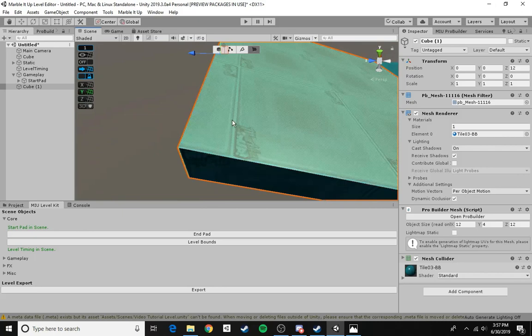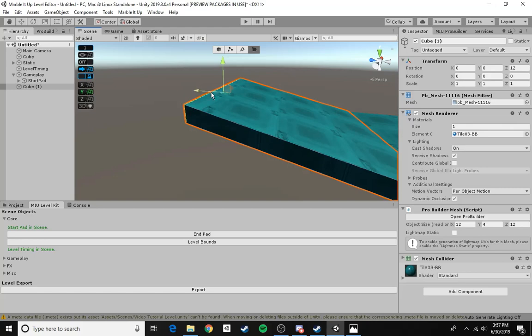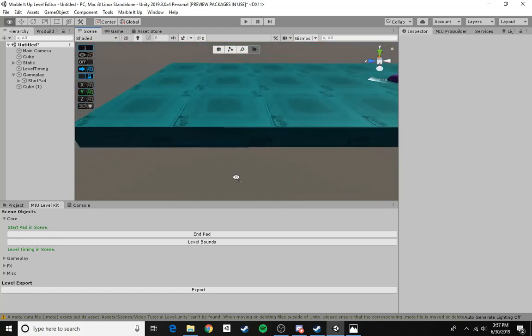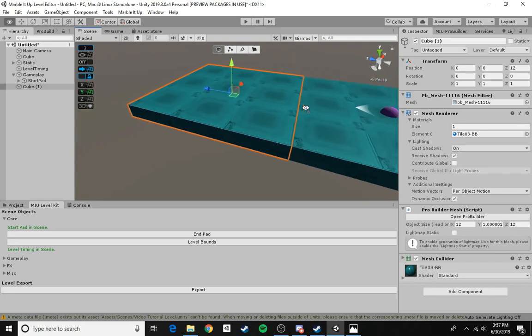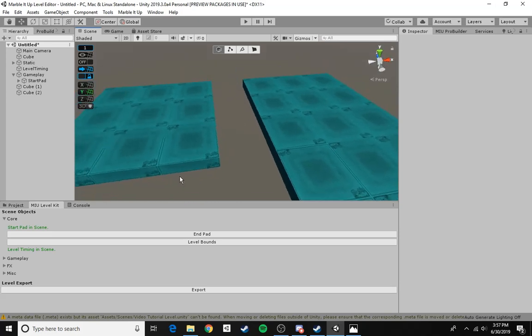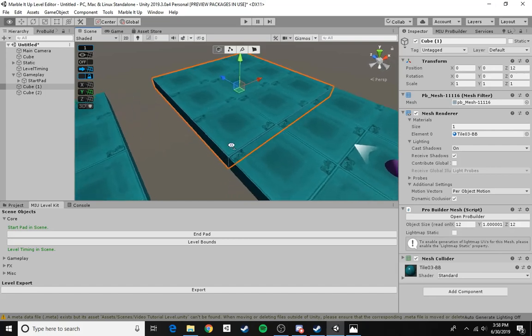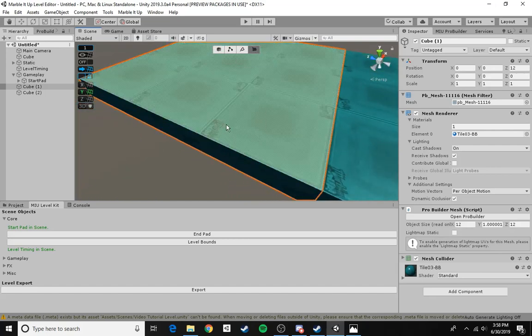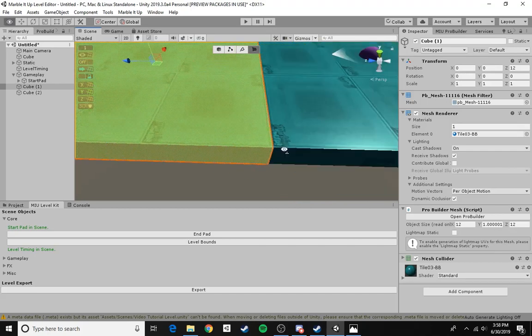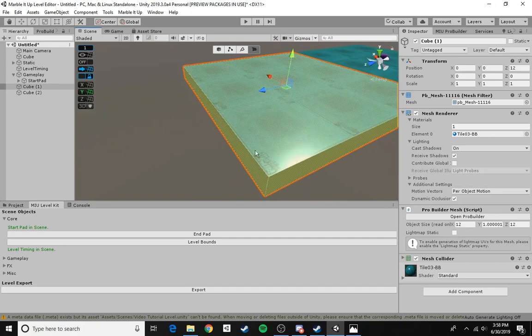You look at the edge, you can see that the texture is starting to get misaligned and messed up. So let's undo, Control Z to undo. How do we fix that? Well, there's two ways. So the first one, we can go to the face selection. If we double click a face, then it should select all the faces on the object. Otherwise, if for some reason you really can't get that to work, just select all the faces. There's only 6. It would only suck if you're on an object with like 100 faces.